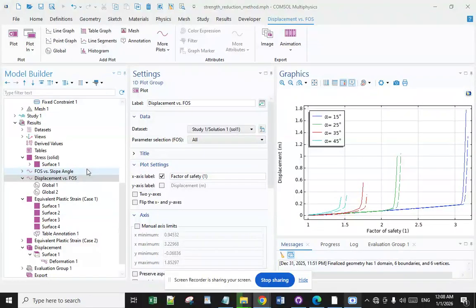Margin of safety as a measure of requirement verification. Many agencies and organizations, such as NASA and AIAA, define the margin of safety including the design factor. In other words, the margin of safety is calculated after applying the design factor. In the case of margin of zero, the part is exactly the required strength.